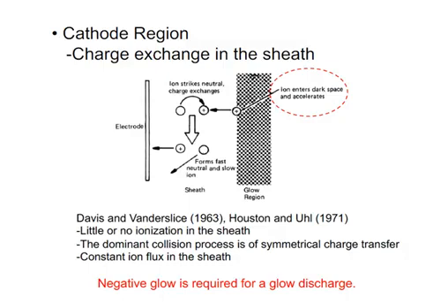So the cation from the negative glow becomes very important. Eventually this cation undergoes replacement reaction and then reaches the surface of the cathode with very high energy, bombards the surface, and causes the secondary electron emission from the cathode, and this process keeps going and going.